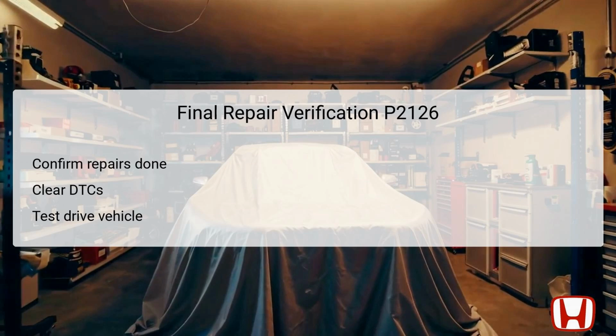Next, clear the DTCs from the system using the HDS to reset any stored error codes. After that, a test drive of the vehicle is essential to ensure that the issue does not reappear, allowing you to confirm the integrity of the repair work. This final verification step ensures peace of mind for both the technician and vehicle owner, reinforcing that the DTC P2126 has been addressed thoroughly and effectively.